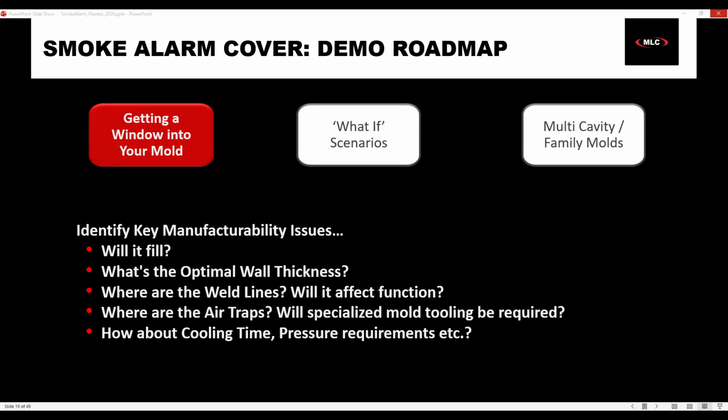As far as meshing goes, this works very similar to other tetrahedral meshing that you would see with FEA. If I go ahead and show the mesh model, this is the generic mesh that it did automatically. Something that's interesting with this is it's still a pretty good mesh. We can make it tighter in some places for sure, but as a first run, we can keep it a bit coarser and then maybe decide to make it a little bit tighter in some places once we have a better understanding.